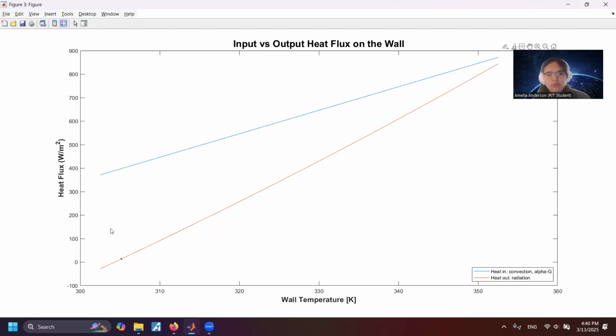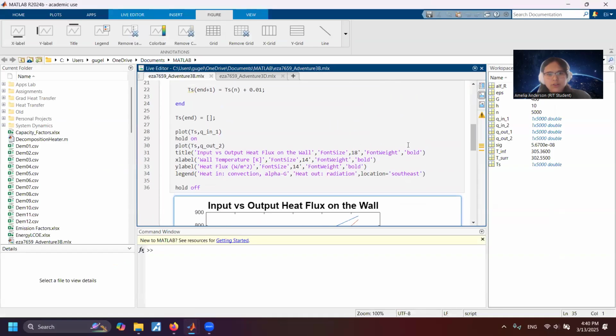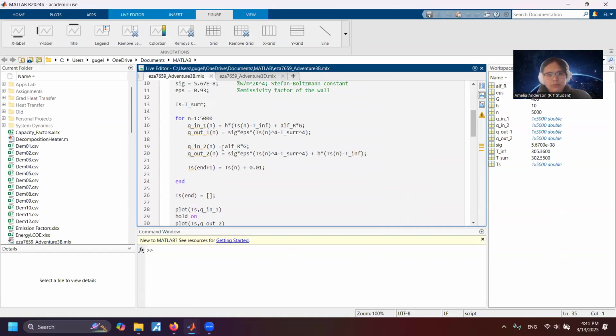So we can assume that because there was no intersection between 302.5 and 306 or whatever, in order to meet our surface energy balance conditions of E in equal to E out, this is not correct. So what I'm going to do is hop down to this one where I assumed that our input energy is only irradiation and all of our losses are from convection and radiation.